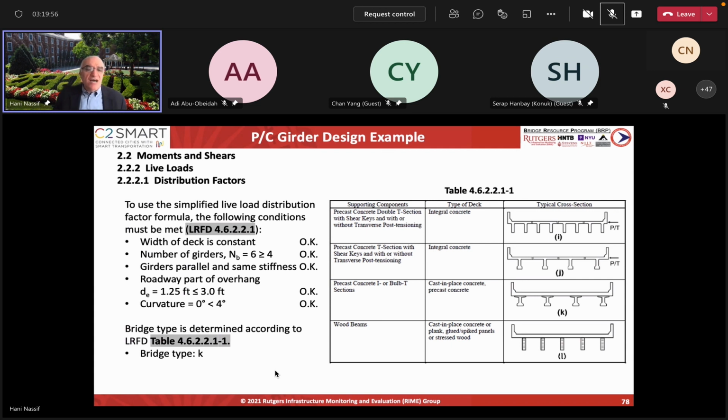So now you have estimated the loads, dead load mainly. Now you're going to figure out how to do the live load. I have a truck, the HL93, and I want to apply that. I can find the moment on a simply supported span, and find the maximum moment. How do I distribute that lane moment for 1 lane or 2 lanes? Depending on the case that I'm considering, I'm going to have to use the girder distribution factors. Let me stop at this point.